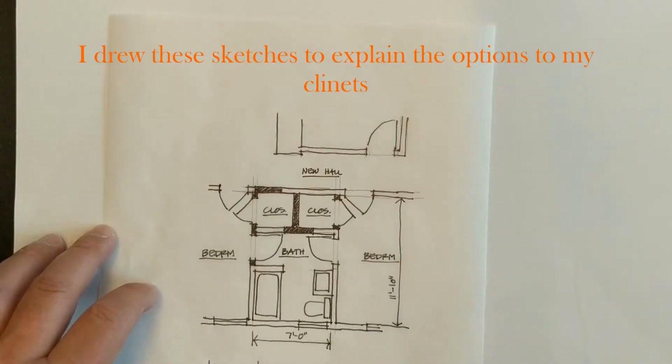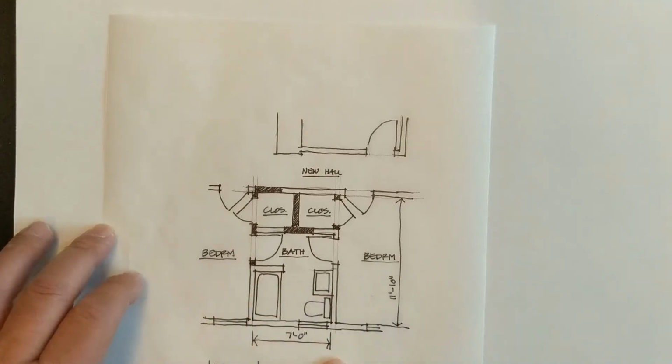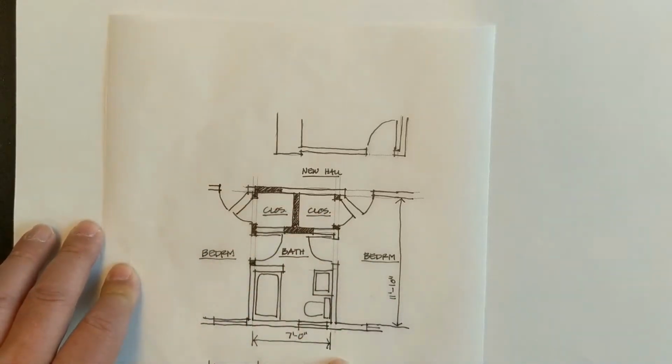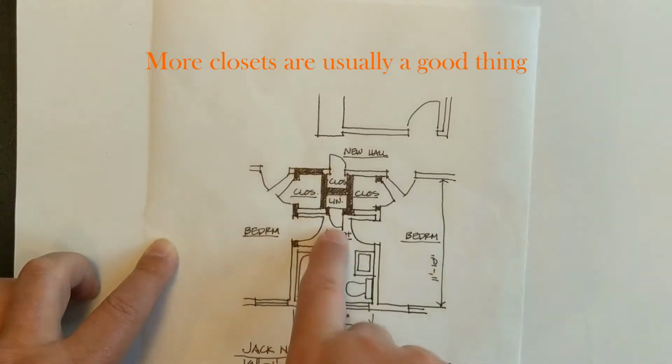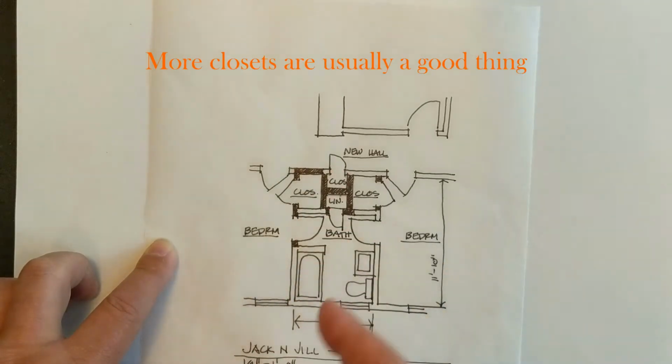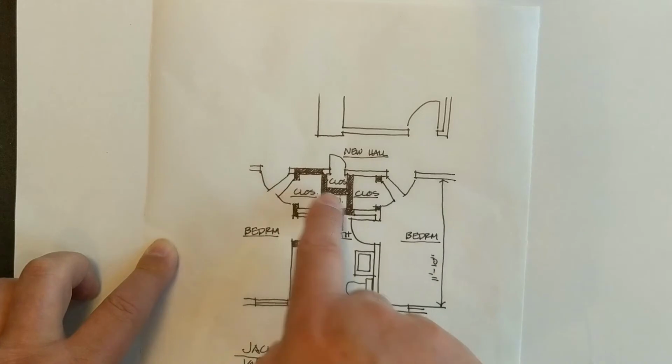This sketch shows a basic Jack and Jill with the space where the hallway used to connect it to the rest of the house being turned into two closets. This is okay. All the plumbing stays in basically the same place. You get two slightly larger closets, but we have some door conflict issues, but we do resolve the circulation. The next thing that I looked at was still the same Jack and Jill, but I was wondering if we could get a linen closet into the bathrooms for other storage and maybe another closet in the hallway. That works too, but we still have the same door conflict.